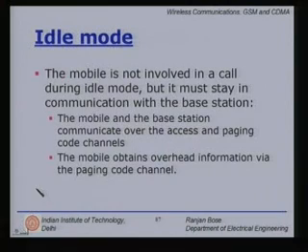The idle mode. This is when the mobile is not involved in a call, but it must stay in communication with the base station, and clearly it will expend some battery power. The mobile and the base station communicate over the access and the paging code channels, and the mobile obtains overhead information via the paging code channel. At this time, there is no voice communication taking place, simply because there is no request for voice.